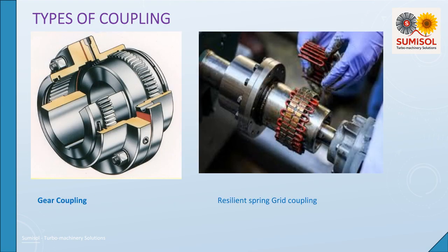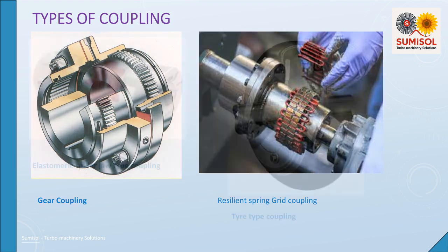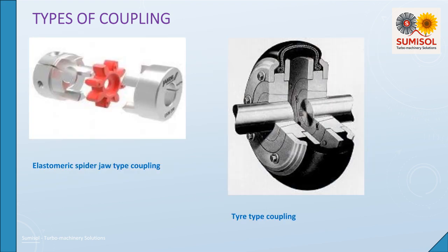Gear coupling transmits very high torques. It transmits torque through splines and accommodates misalignment by clearance between splines. It requires regular lubrication. Grid-type couplings have the following features. They transmit torque through a spring set between splines. The spring provides torsional resilience and accommodates misalignment, axial sliding, and bending of the spring. They require regular lubrication.